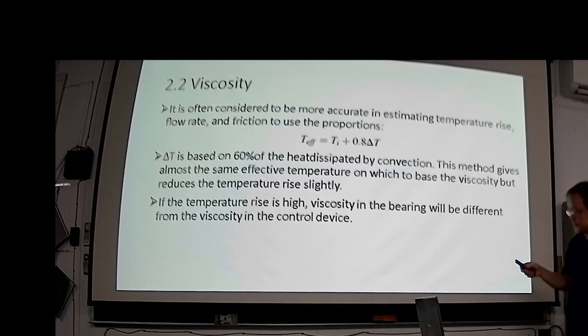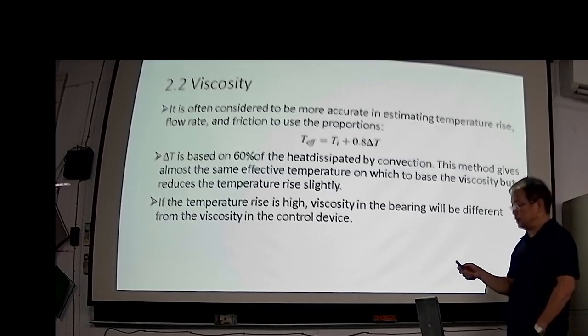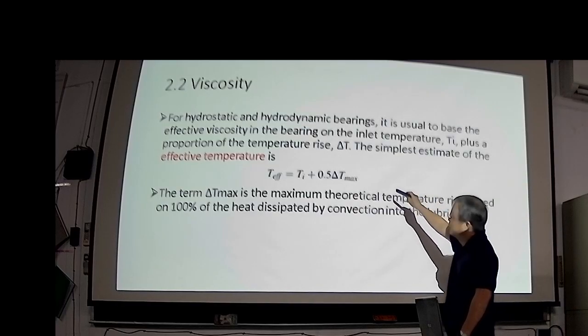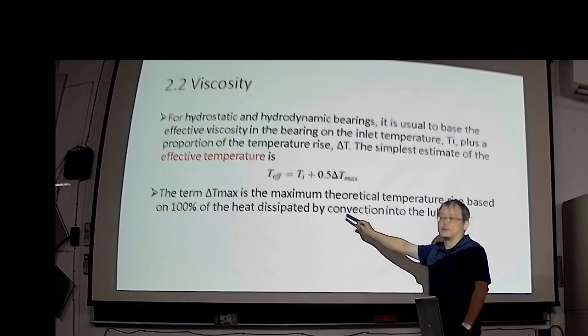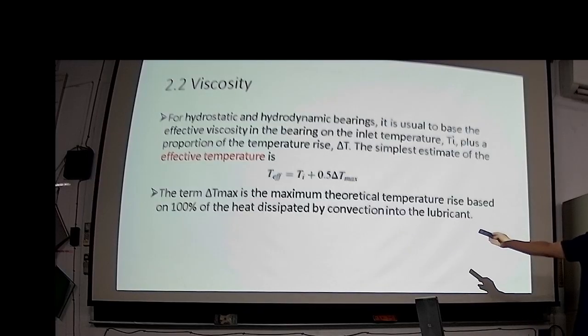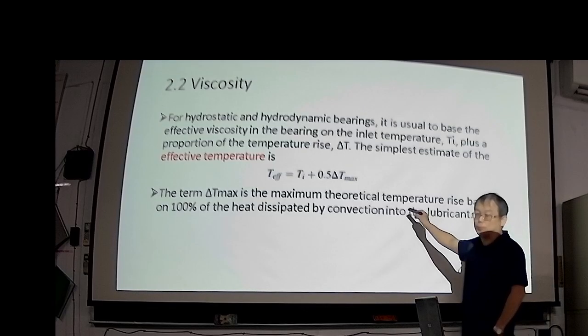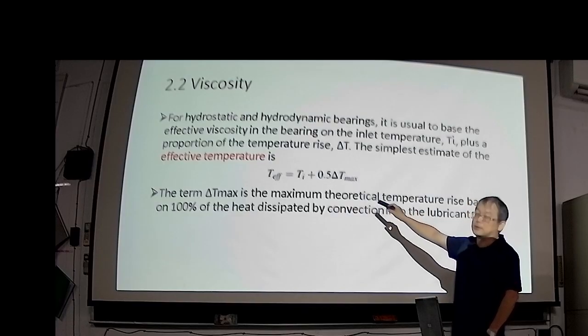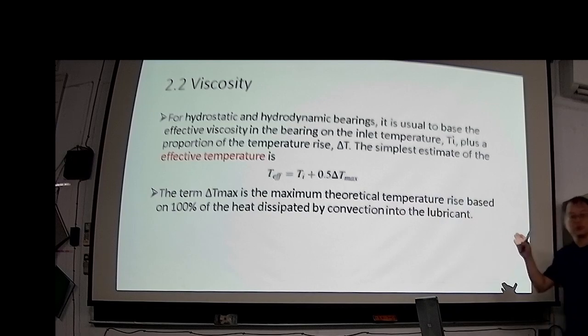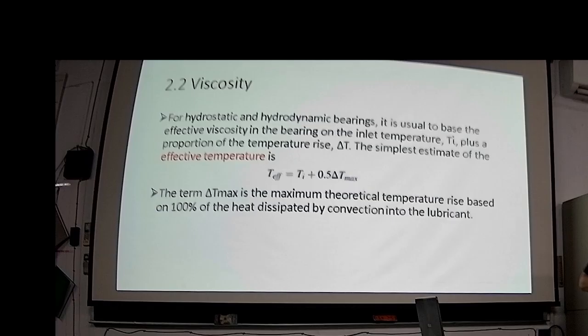But in any case, in theoretical calculation, you can use this one by assuming 100% of the heat generated by the viscous friction between two bearing surfaces is convected to the lubricant, using this formula. This is the worst case scenario for the calculation.